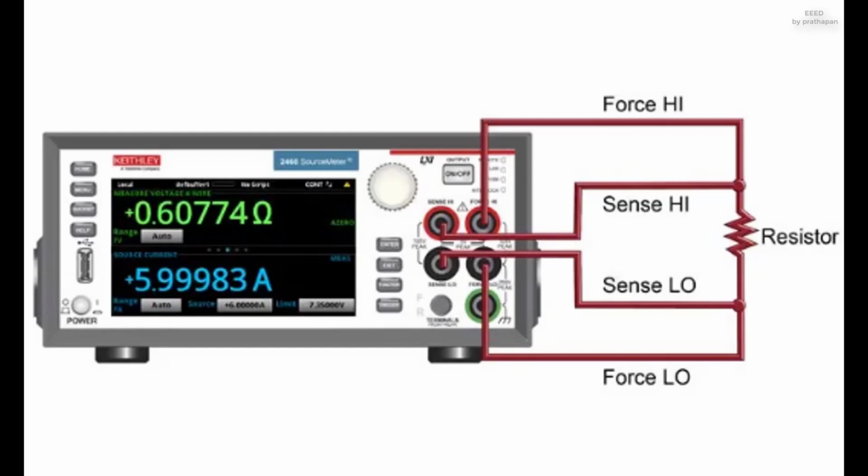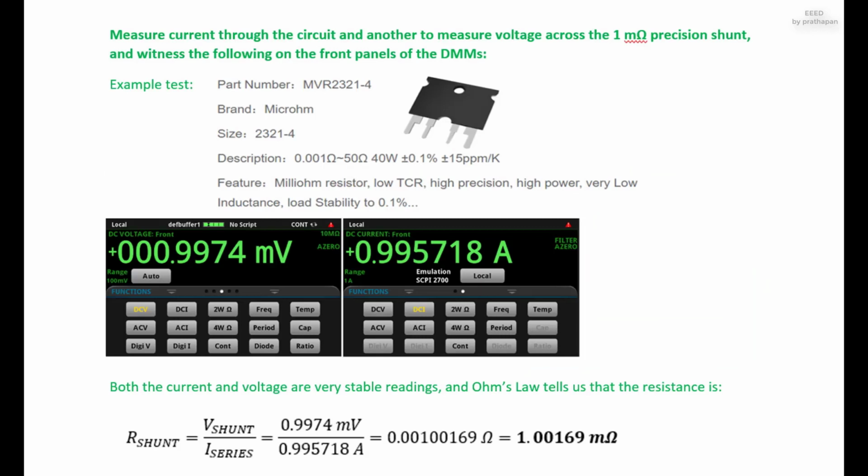A digital multimeter, using active electronics, may instead pass a specified current through the test resistance. The voltage generated across the test resistance in that case is linearly proportional to its resistance, which is measured and displayed. In either case, the low resistance ranges of the meter pass much more current through the test leads than do high resistance ranges, in order for the voltages present to be at reasonable levels, generally below 10 volts, but still measurable. Measuring low-value resistors, such as fractional ohm resistors, with acceptable accuracy requires 4 terminal connections.